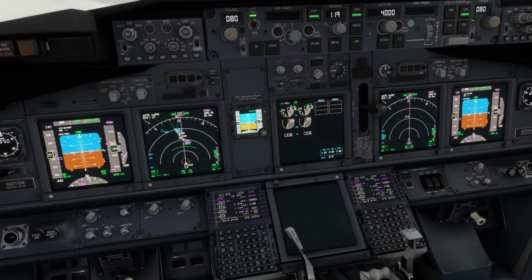Yeah, what JP says is correct. On the 737, if you lose system A on takeoff, for example, the gear transfer unit will let you retract the gear. Yeah, that's the point. Because in this case, we cannot retract the gear. But in case you lose the engine as well, then you can do it. I don't know if it's only on takeoff, but it's very specific, okay, Douglas? It's very, very specific. It's like a disaster situation.